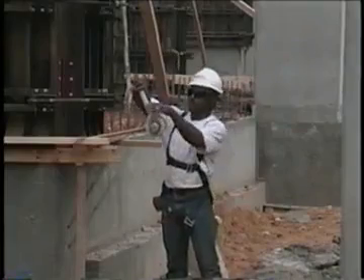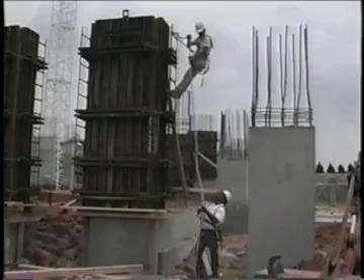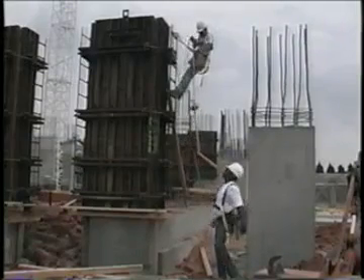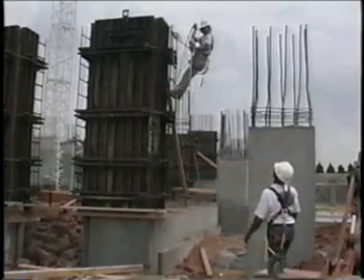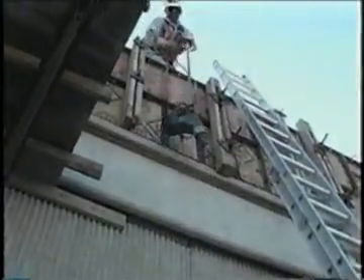When additional tools or materials are needed, they must be sent up on a rope or in a bucket. The person on the ladder could fall off trying to catch something thrown to him, especially if he has been trained to instinctively reach out to make a catch. Electric tools may not be raised or lowered by their cords, since this may damage the tool and the defect may not be discovered until a painful shock occurs.